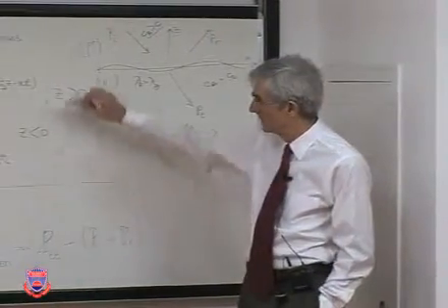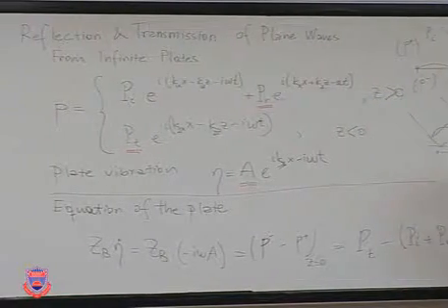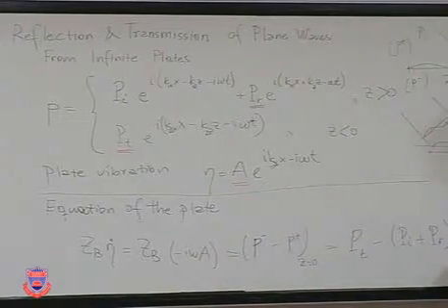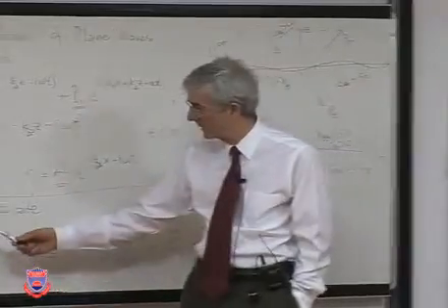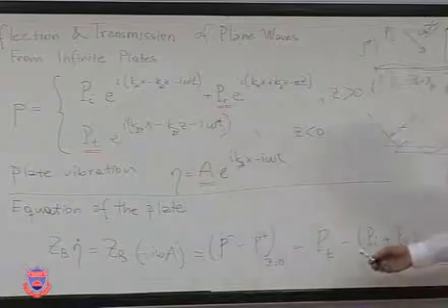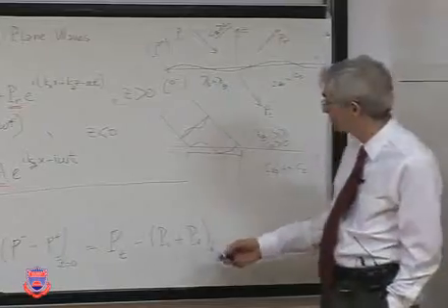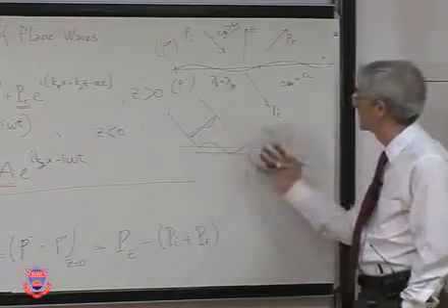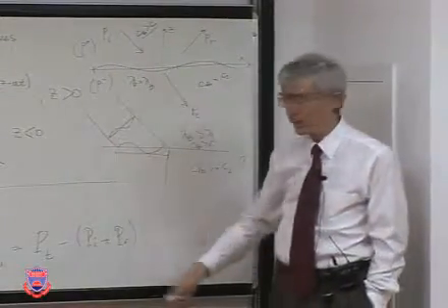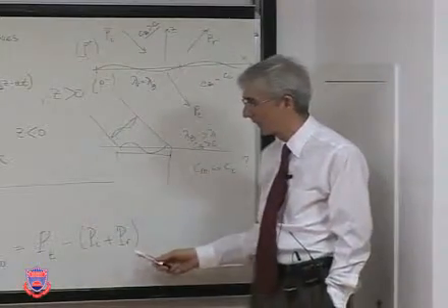Now, again, we have the expressions, we have the displacement for the plate, and the next thing we do is write the equation of motion for the plate. An equation of motion meaning velocity times its impedance is excited by the pressure on both sides. Positively, because it's from under pushing it up. Negatively, because the top is pushing it down. And from the top, it's incident and reflected waves together.